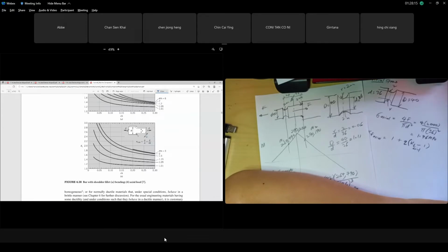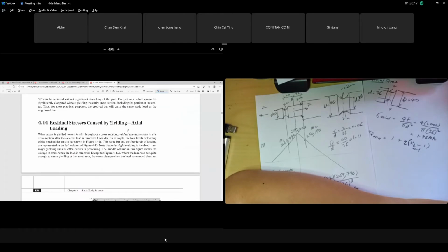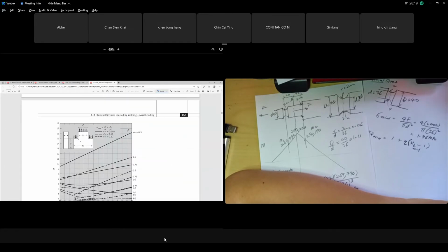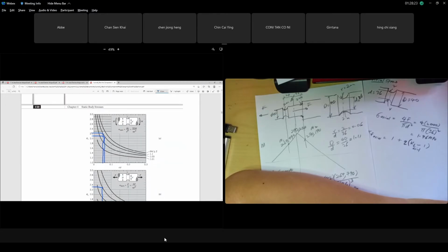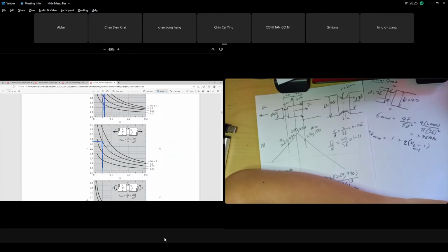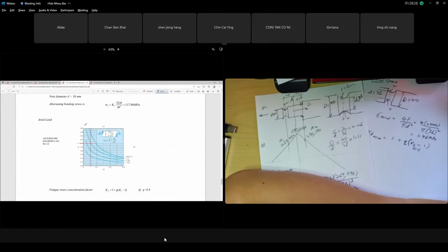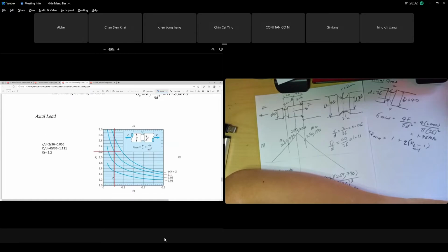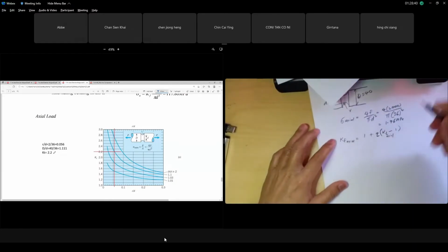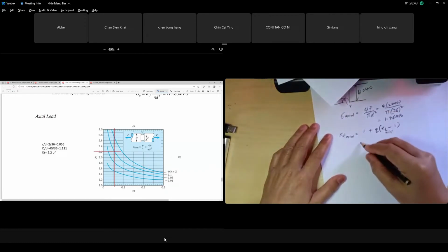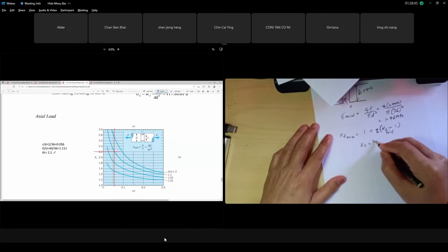No, this one plate lain. Plate is not sharp. This is the consideration. Okay, tak apa, never mind. Okay, let's say kita go for the solution given tu. Actually kalau axial 2.3, tak apalah. So you get it from dia punya graph ni, from your solution. Dia punya ni, the got is 0.056, bring it, got 2.2. Nampak tak kelas, so KT is 2.2. Do you understand or not? Kelas, go for axial. So your KT tu is 2.2.